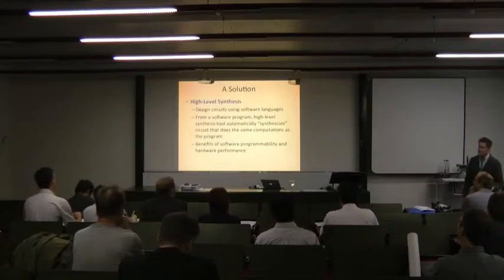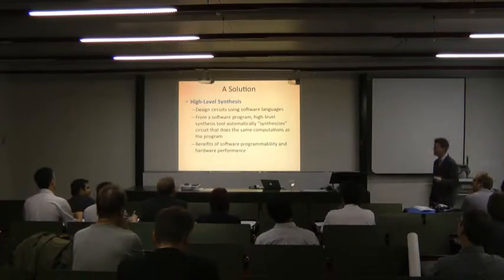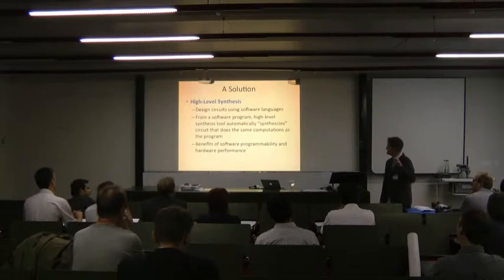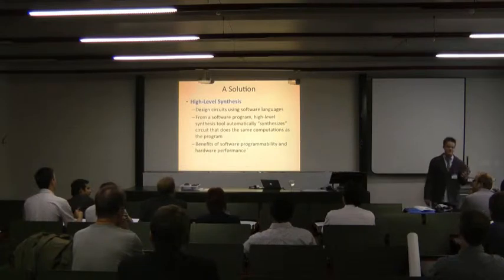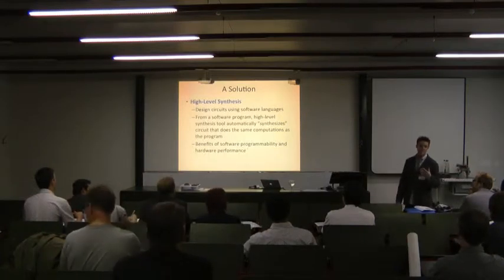And so a solution to that is, of course, high-level synthesis. You're going to design circuits from software languages, from a software program. With high-level synthesis, you automatically synthesize a circuit that does the same computations as the program, giving you some of the benefits of software programmability, with some of the hardware performance and power benefits.